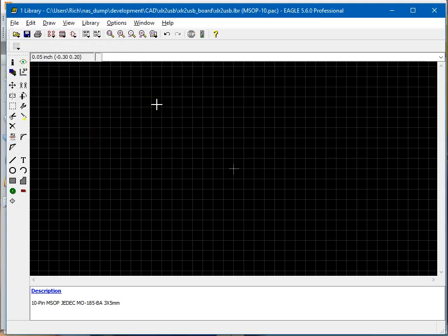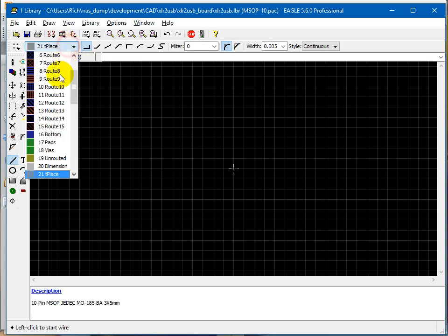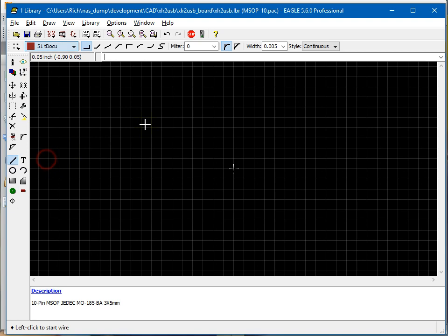That's my personal one. And the nice thing is when I go into the CAM process of building the actual manufacturing files, I will get a Gerber file that's dimensionally accurate that shows the placement of each component. So we'll use our wire command because we're just drawing documentation, and we'll do it on our tDocu layer. Because these aren't physical lines, they don't get put down in ink anywhere, they're just lines usually on a paper or a Gerber file. I can set the width to be 0 and have no problem.